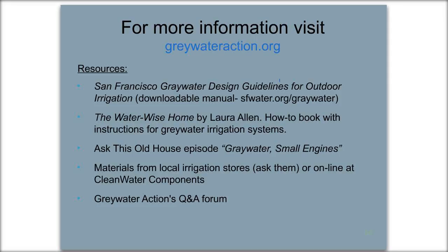What system is best for watering a lawn without a major remodel? You can't really water a lawn with a graywater system without getting all the water and having a sophisticated system. You can, in practice, carry buckets of water and dump it on your lawn. You're not really supposed to, well, if it's in the bucket, it's not technically graywater. There's ways to do it, but there's no way to do it without a very manual system. And to do it legally, you'd have to remove the lawn, have a filtered graywater system, put in subsurface drip, and then put the lawn back down.